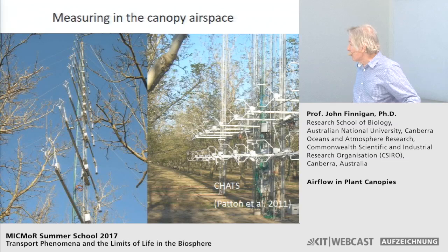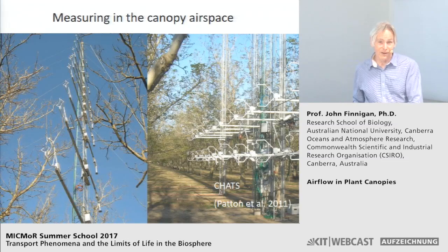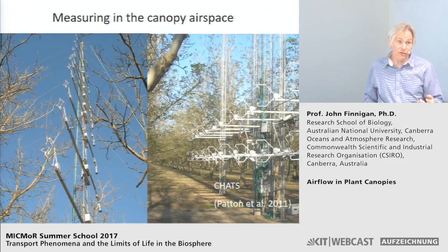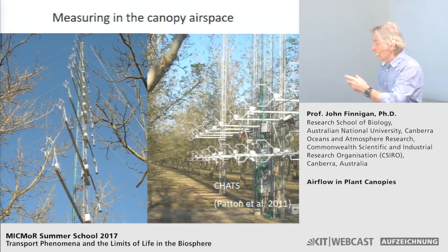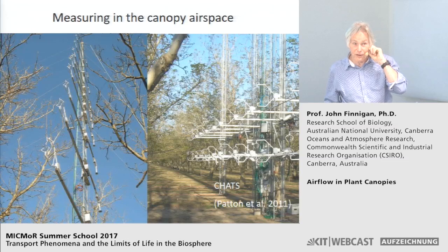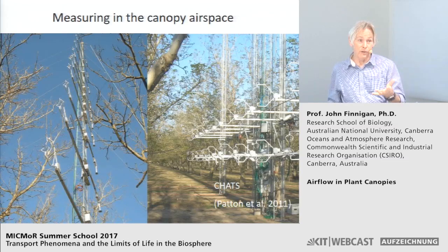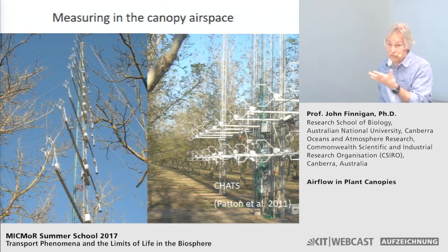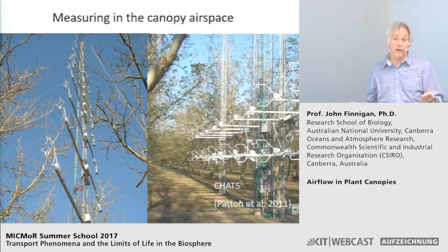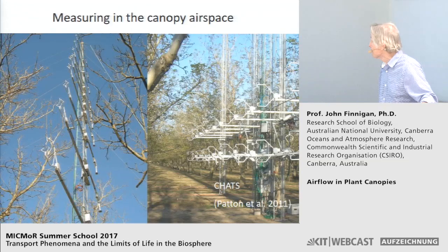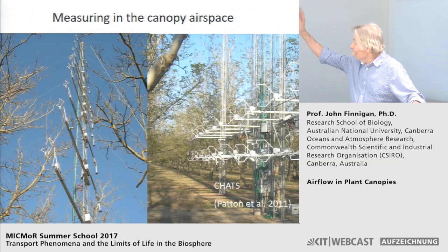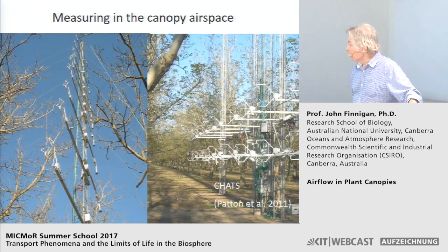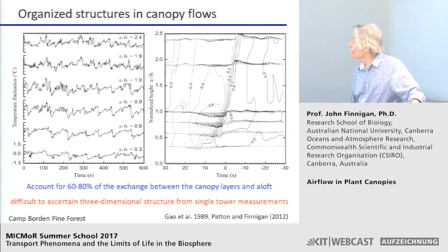When we were trying to do this kind of stuff in the 80s and early 90s, we could only drool over having this many anemometers, not only to deploy, but actually anemometers that work, because in those days, you usually spent most of your time going up and down towers, fixing transducers which stopped working, and so on. Or it rained, and then you'd have to go up with plastic bags, put plastic bags over the sensors, or else it wouldn't work for the next 3 weeks. So we could measure profiles at different levels through the canopy and above.